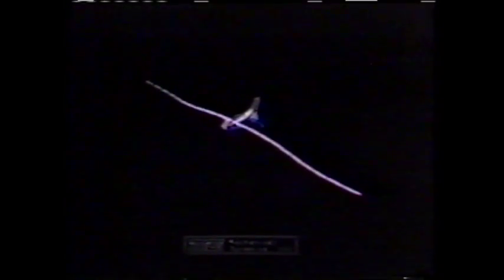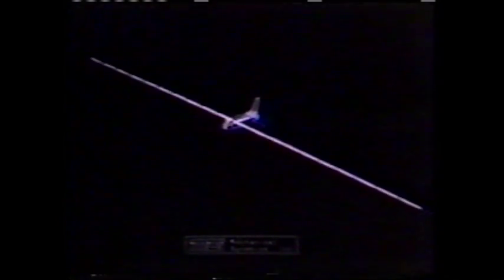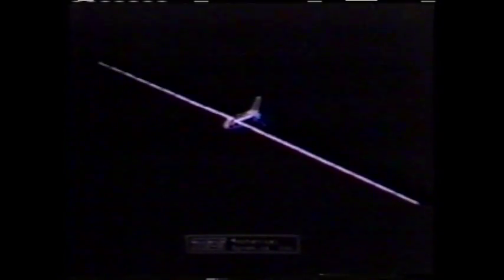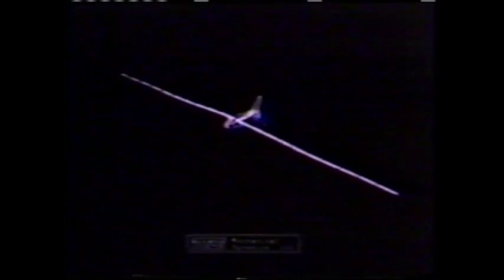This last example demonstrates a new and very powerful capability in ATOMS to model flexible components in a nonlinear large displacement environment. In this model, a 300-meter highly elastic dipole antenna has been strung through the shuttle. What the engineer wants to know here is how the tip and intervening segments of the antenna will behave when the shuttle's attitude thrusters are fired.